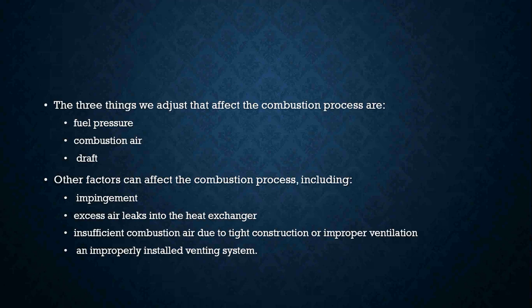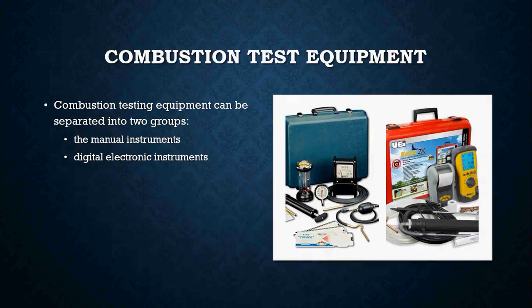Improperly installed vent systems are usually not a problem, but it depends on who puts it in. If Johnny homeowner likes to put stuff in by himself, chances are they probably screwed up the venting system. One thing when it comes to venting is that you want to try to keep it as straight as possible with as few turns as possible.